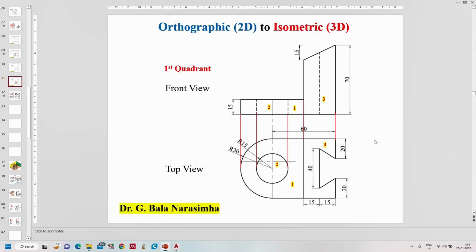As I said in the previous tutorial also, to construct we always have to look at the true profile. In the front view it looks like a rectangle, and with a rectangle and lines we can't do the construction. So always start with the true profile. You know that this complete length is 60, but here they gave the radius as 30.